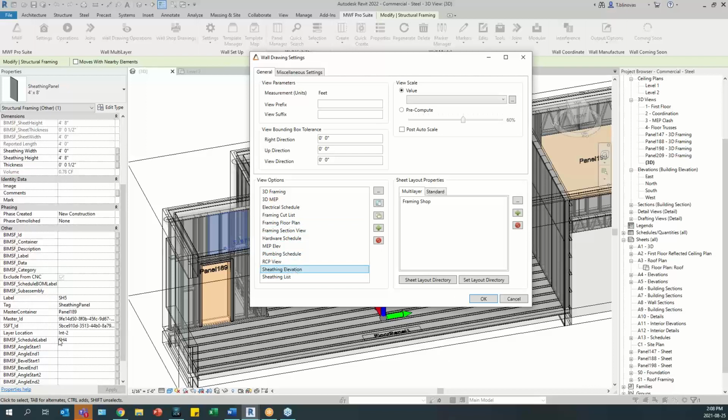I would say that now that we can label automatically the sheeting, it would be a good idea to just generate a specific view for that instead of adding both sheeting and structural members in the same view. The only reason why is because the labels will be probably overlapping each other. You will get a lot of information if you don't separate the views. So that's why I just created one for my sheeting, so we can see only the sheeting information.